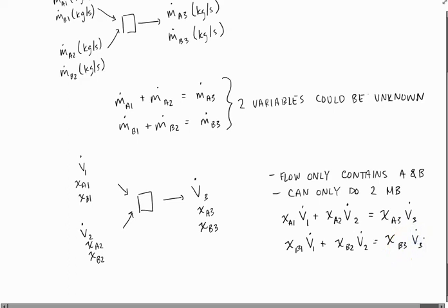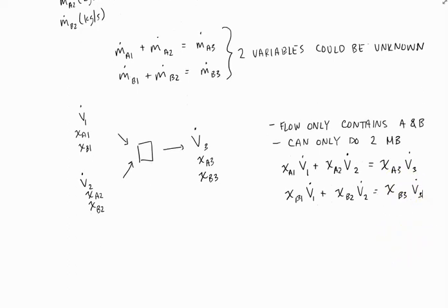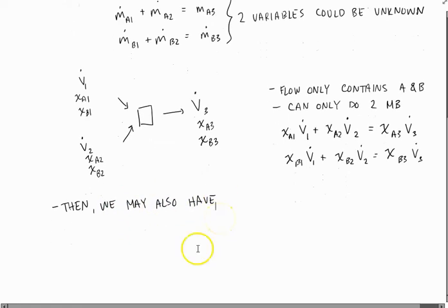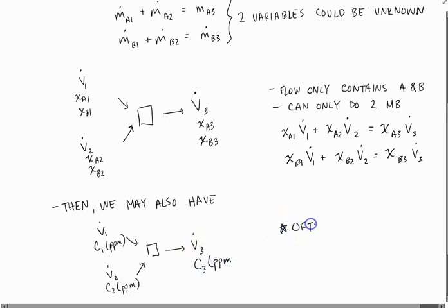We have also talked about V dot and some sort of concentration. Very often in environmental engineering, we have carrier fluids like water or air, and in general, we're looking at relatively low concentrations of something within those carrier fluids. So while in chemical engineering, mass flow rates of each of the components or fractions of each of the components are very common, in environmental engineering, we more often see these volumetric flow rates with concentrations.